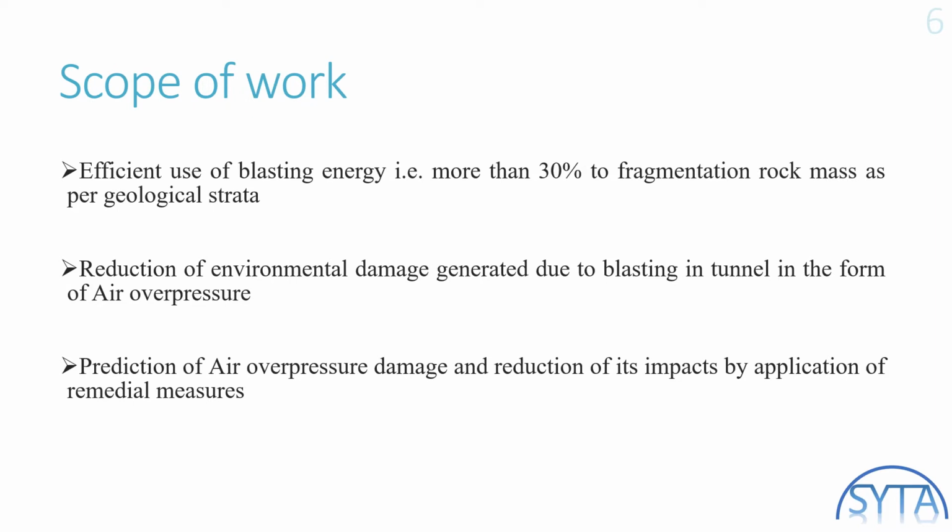Scope of work. Efficient use of the blasting energy, that is, more than 30% to the fragmentation of the rock mass as per the geological strata. The reduction of the environmental damage which is generated due to the blasting inside the tunnel in the form of air overpressure. Prediction of the air overpressure damage and the reduction of its impact by application of remedial measures. These are the scope of my work.